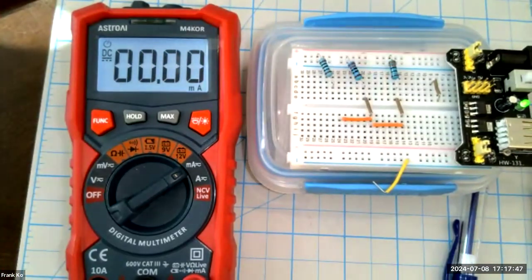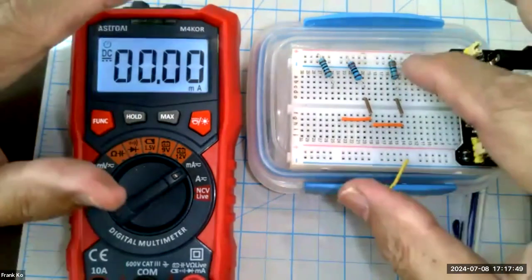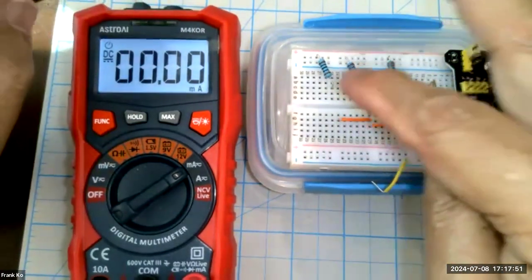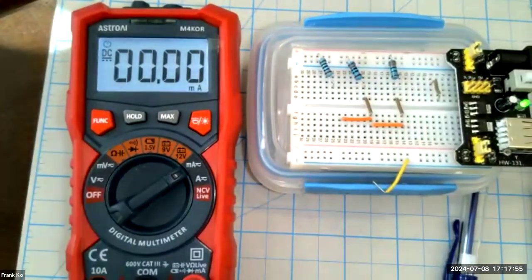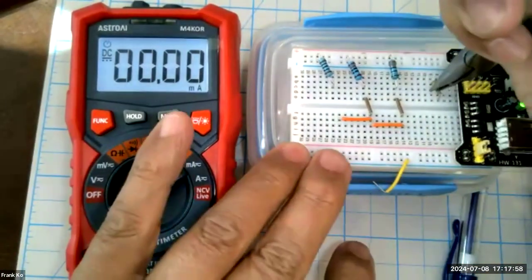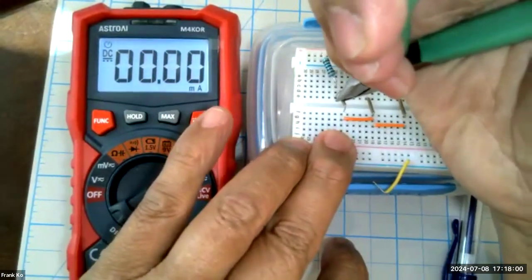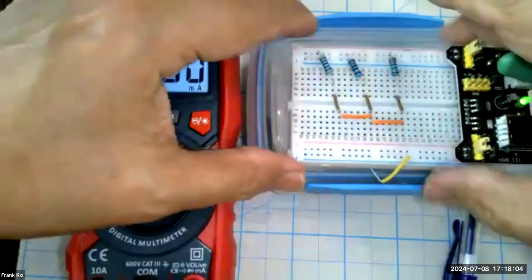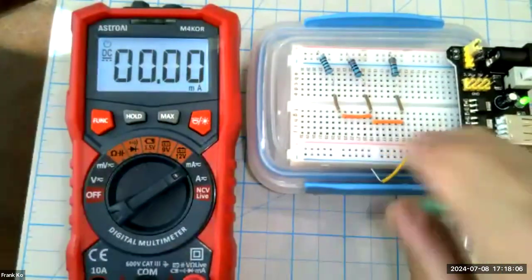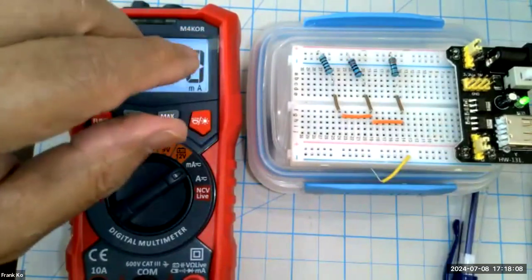We are spot on. So that's how easy it is to measure total current and each of the branch currents for a fault condition if you subscribe to the neat circuit building method that I've been promoting all along. And that is your resistors cut, bent, and using jumper wires in a fashion that is easy for you to follow.